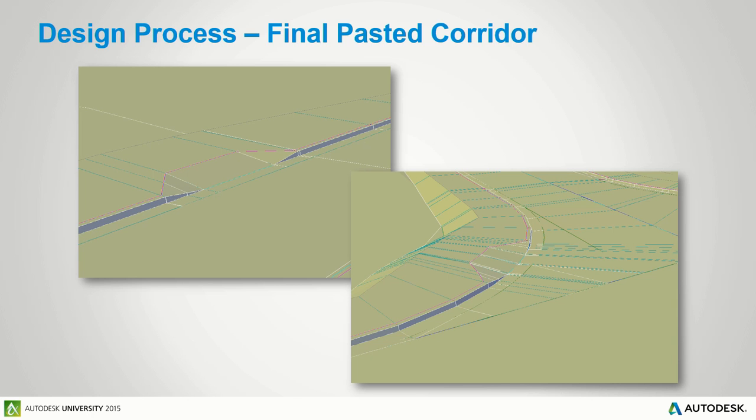So yeah, great thing about that, unlike using feature lines, they're dynamic, they're part of your corridor. You just got to drag your grips around. You can pretty much move them, stretch them, make them as long or as short as you want. And most importantly, they just stay linked to your alignment. So the rework time is just so much less than using feature lines.